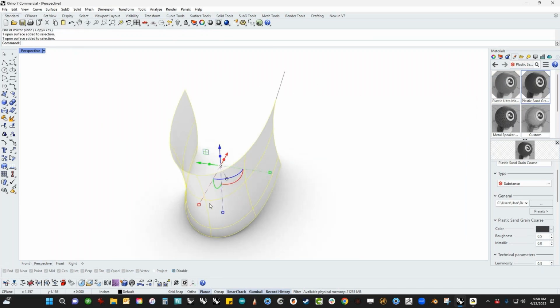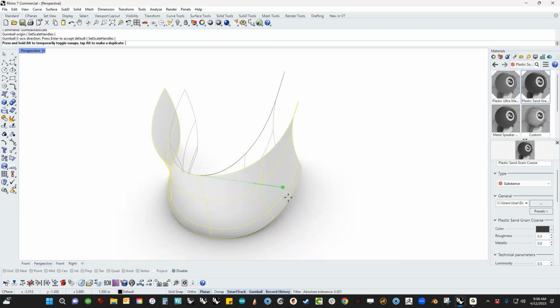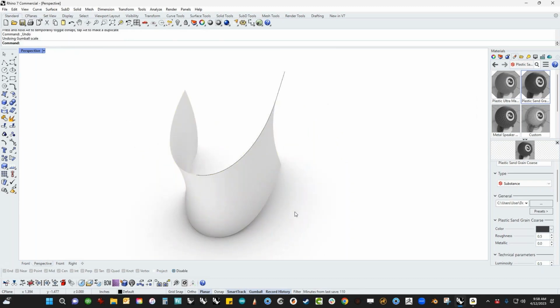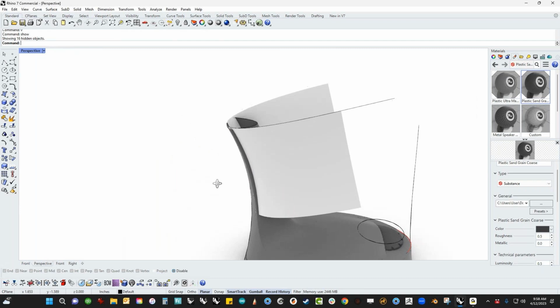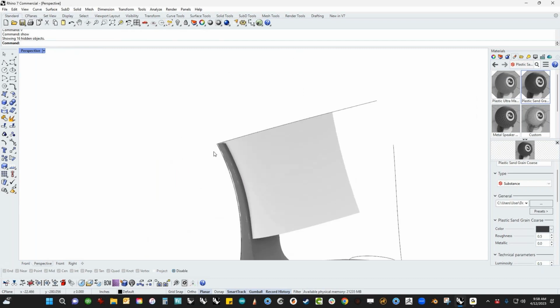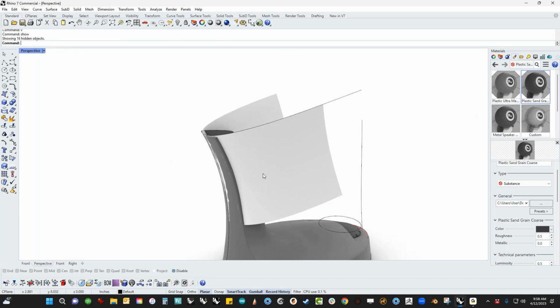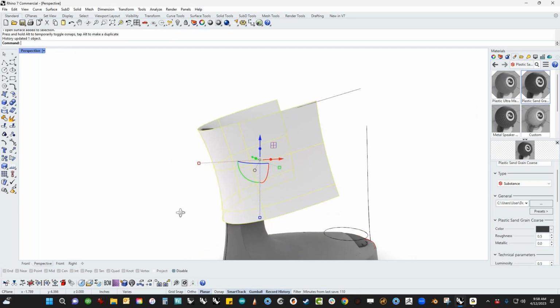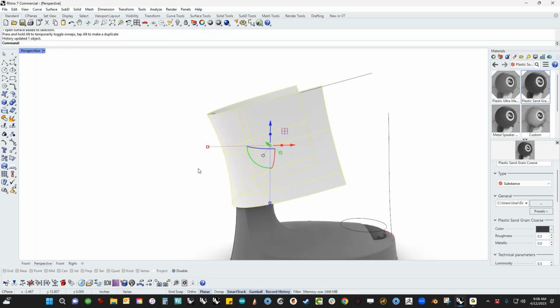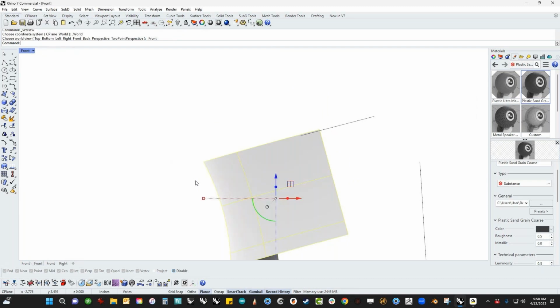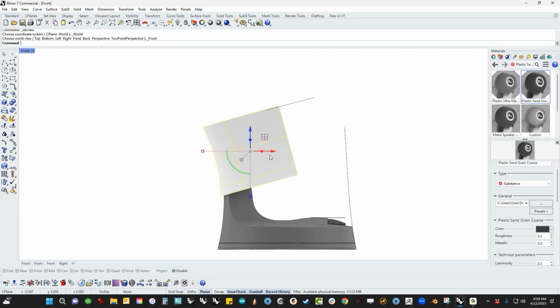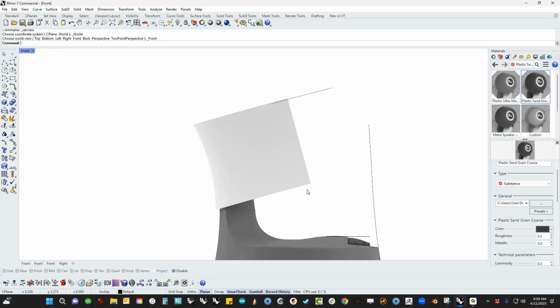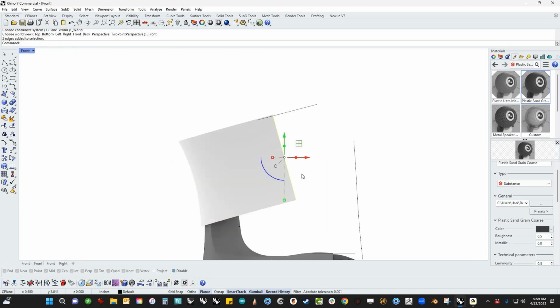And so I can stick my gumball right here with gumball relocate, and then I can decide how wide that is. So let's bring the base back and take a look at it and say, okay, how do these relate to each other? Now, this is overbuilt, so I've got more than I need. I think I'm going to have this just tuck past it a little bit like it does in the actual part. And in this case, it looks like this edge might need to come out a little bit farther like that.